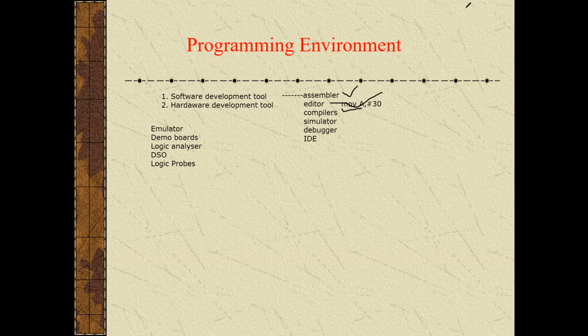An emulator is a combination of hardware and software, and it consists of a multi-wire cable that connects the host system to the external system. Through this cable, the emulator software allows the user to download the object code program into the RAM of the external system which is being developed.